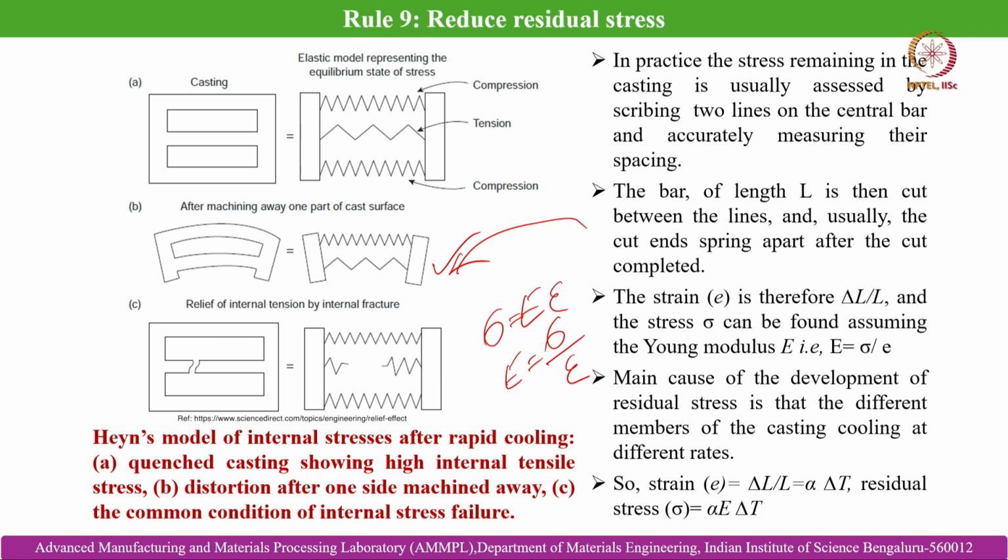We will also discuss how we can design the different subsections of the cast part effectively so that we can reduce this effect. Although we cannot completely eliminate it, we can significantly reduce the problem of having different cross sectional attributes at different locations within the cast part, which results in differential cooling rates at different sections.